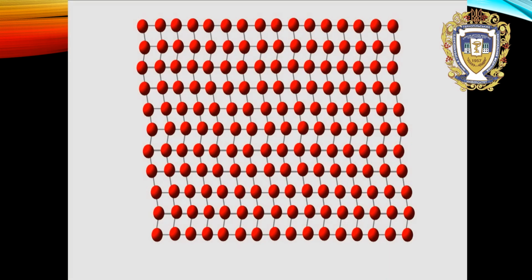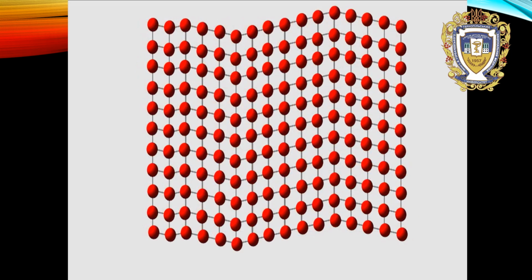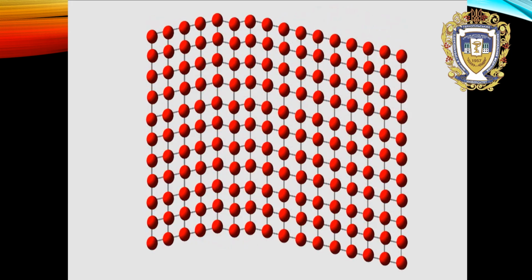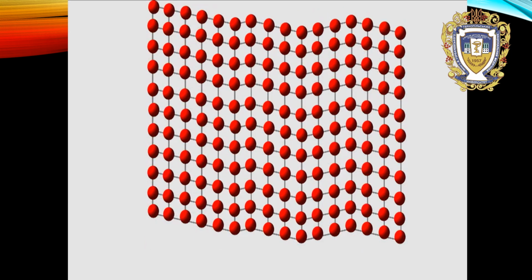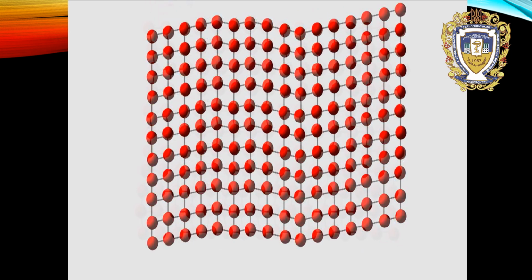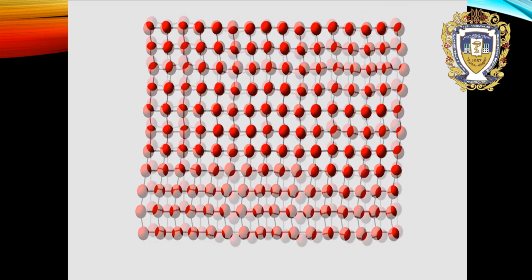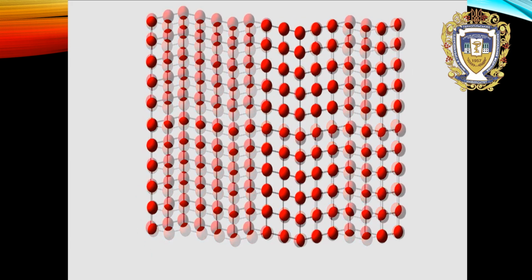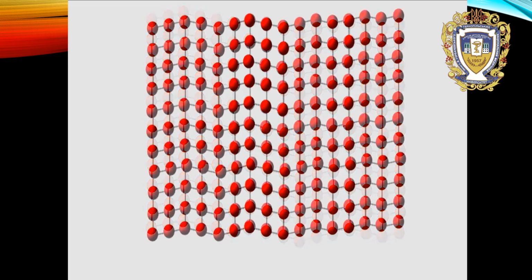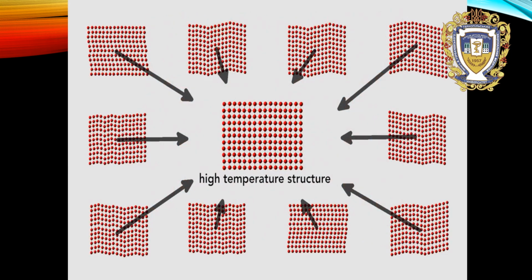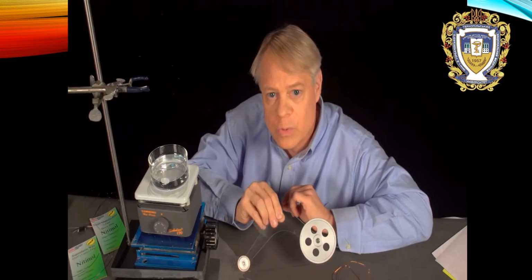You could imagine that in response to different forces, in a large enough crystal there would be hundreds of mixtures of these two rhombuses, and many, many more in a three-dimensional structure. But notice this. At all times, the atoms are connected in the same way as in the high-temperature phase, unlike in slip, where atoms can rearrange quite a bit more. So when the temperature is raised again, these rhombuses, no matter how they are distributed, return to tidy squares. The only structure that can result is the original structure, and so the nitinol reverts to the shape it had at high temperature.